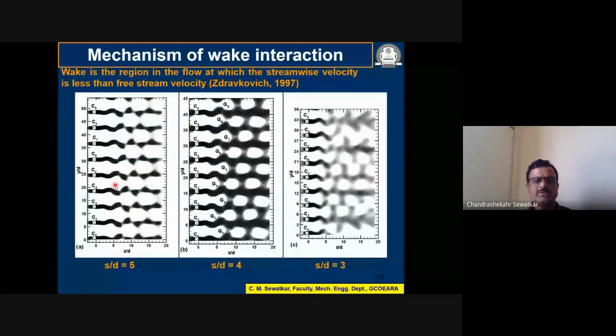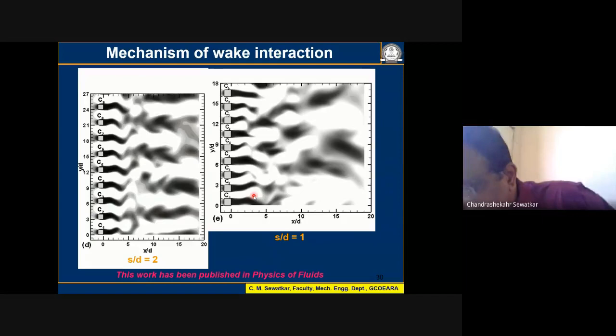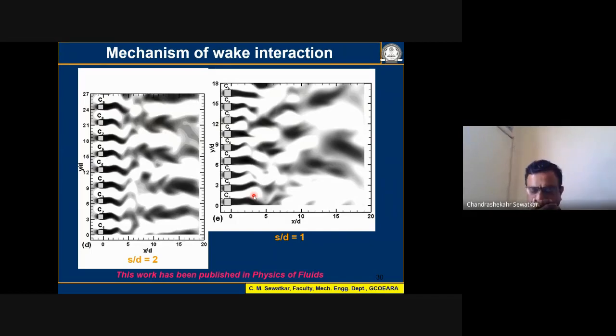And that is happening because wakes are independent, wakes have structured interaction. Few wakes are broken, all the wakes are broken. So the moment I keep on reducing the spacing between the cylinders, the wake structure completely breaks, and that leads to a chaotic variation of the forces.